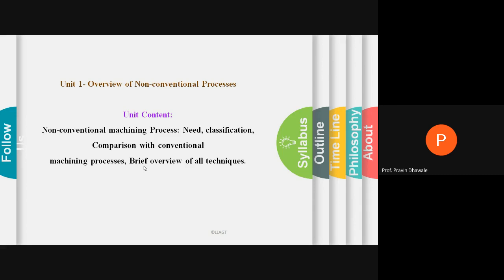And we provide a certain depth of cut to that tool so that material is removed from that cylindrical workpiece. Here you must have a cutting tool. The material of the cutting tool must be harder than the material of the workpiece, right? Then you must apply a cutting force on the workpiece, meaning you have to give feed to the cutting tool or depth of cut. Otherwise, material is not removed from the workpiece. You must give a certain depth of cut or feed, also called the cutting force. Then only is material removed from the workpiece.